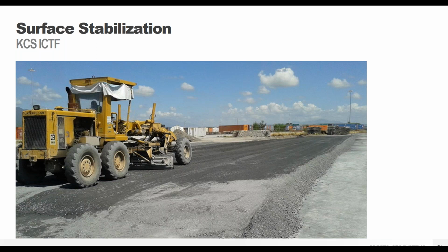That stuff's not going anywhere. But if you do that, you have to realize you're going to have less water infiltration. So, it's a bit of a give and take. Find out what's best for your site, but it's absolutely an option if you want absolute zero movement of those particles.